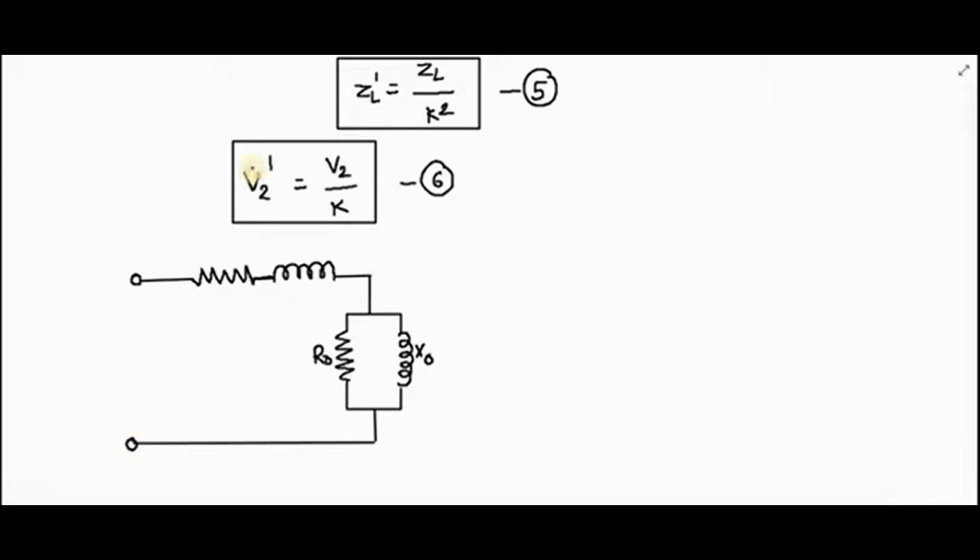Right? Here you have applied the voltage V1. What is this? R1. What is this? X1. Current taken from the supply is I1. Current flowing through the shunt circuit is nothing but I0. Now, let us consider the secondary side. We have to eliminate the transformer winding, which are showing us the ideal transformer. Now we have transferred all the quantities of the secondary side on the primary side.